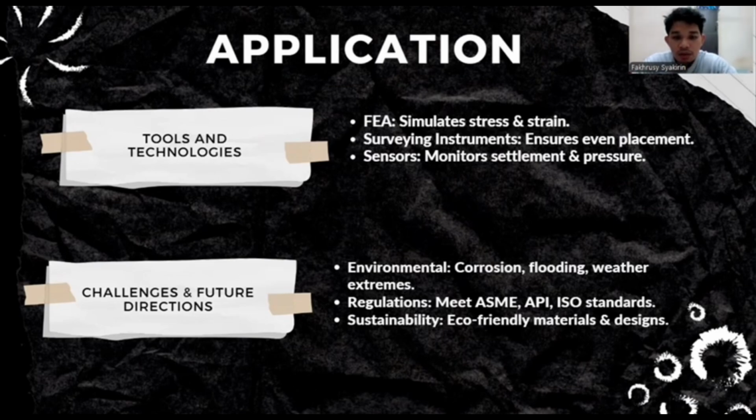Surveying instruments are used to ensure precise placement of the tank and foundation, facilitating even load distribution. Additionally, sensors are increasingly used to monitor settlement and pressure change over time, providing real-time data that can be used to assess foundation performance and prevent potential failure.